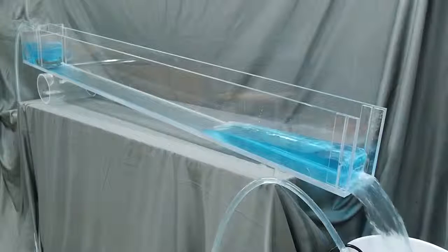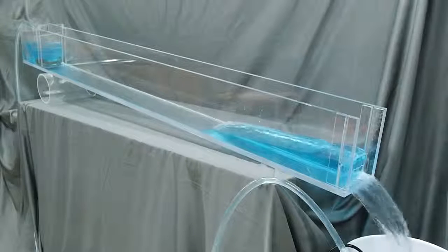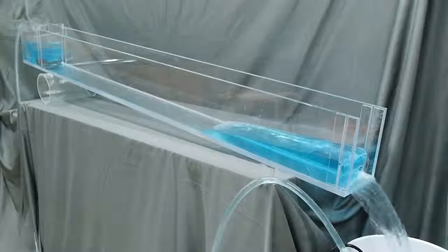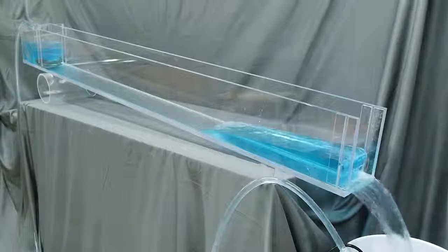But jumps aren't just natural phenomena. They're important in hydraulic structures as well, especially for energy dissipation. A major part of the job of a civil engineer working in the field of hydraulics is designing against erosion from the flow of water. When we try to control the flow of water, that often leads to the potential of having fast-moving, erosive conditions.